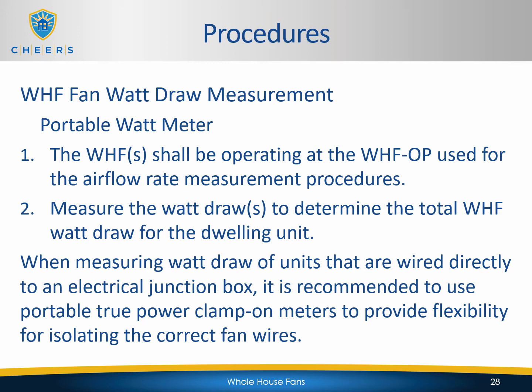Now depending on access and how close you can get to these, there's a lot of different things that are going to come into play as to which method you're going to use. The easiest is likely going to be the utility meter, simply because you don't have to go traipsing up through the attic trying to find where the whole house fan is and finding the wire that's feeding it and clamping on and all of that. It's just as easy to be down outside at the junction box or the electrical panel and just use the utility revenue meter to measure that watt draw.